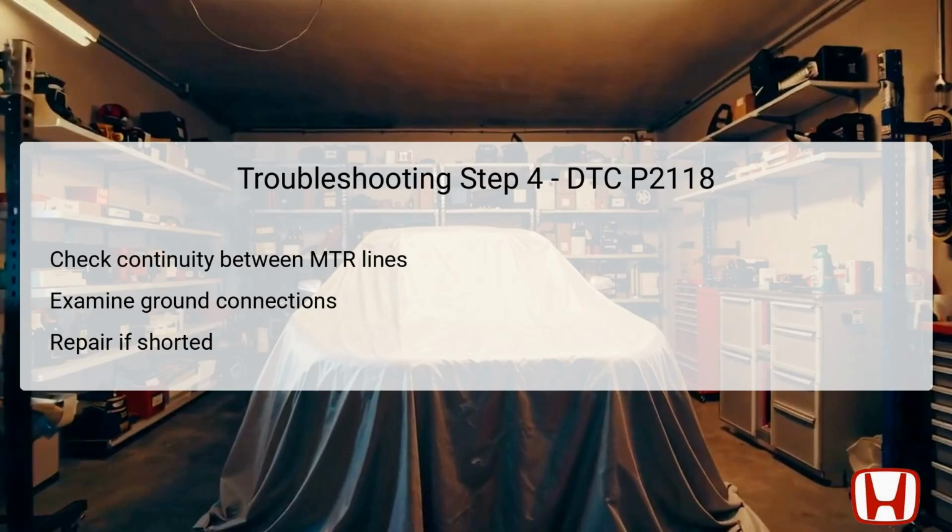to ground, necessitating repairs. In contrast, a lack of continuity suggests these wires are intact, and the technician can proceed to the next step to investigate other aspects. This meticulous approach helps pinpoint wiring issues contributing to DTC P2118 and secures an efficient resolution.